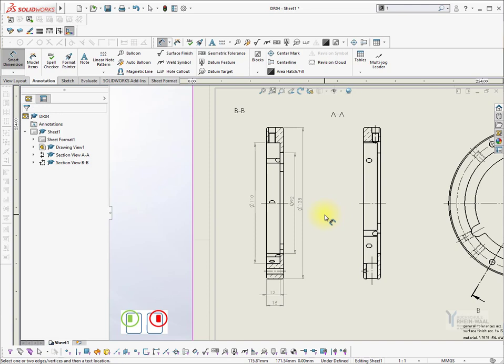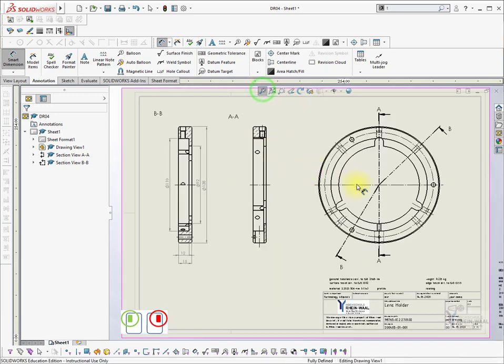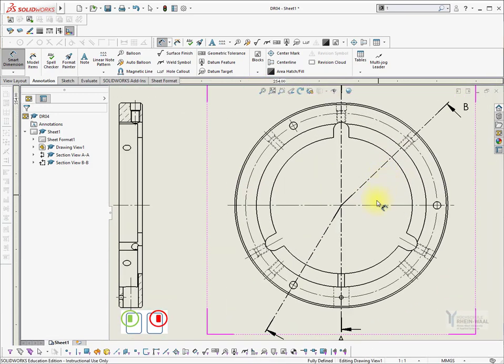Put dimensions of a common step as far as possible on the same view to make it easier for the reader of the drawing. On the other hand, describe the feature where it can be seen best. So for further detail cutout, we take the front view.